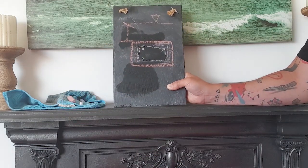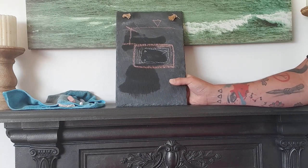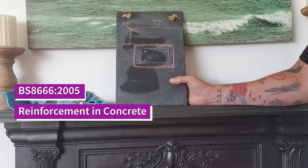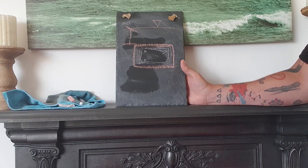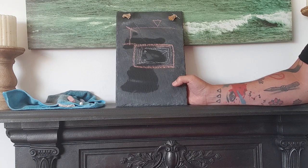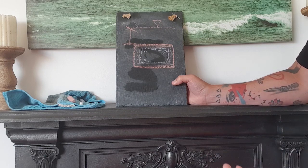And when I talk about links and straight bars in code form, for example, if I say a 51 link or a 00 straight bar, those codes like 00 or 51, come from a specific document called the BS 8666. Now, if you download and look at the BS 8666, there is a shape assigned to the code. Okay? I know it sounds quite complicated, and it is. It's a dark art, but it is something to look at so you understand when you're on site or when you're doing a model for someone, when they talk about rebar codes and rebar bending schedules, you'll have a grasp of what they're talking about.